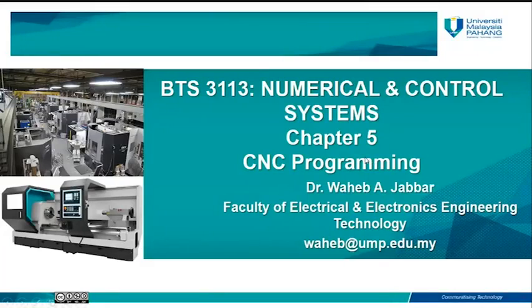Use it there or there, in turning, in milling, in drilling. If I use the G code, it is the same G code. But for some operations, I don't need to use all the G codes that I know. For example, in milling and turning, we don't need to use G17, G18, G19. In milling, we don't need to use G32, like this one.